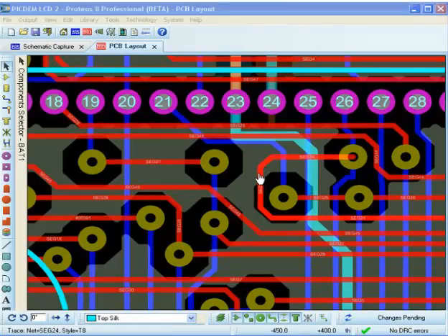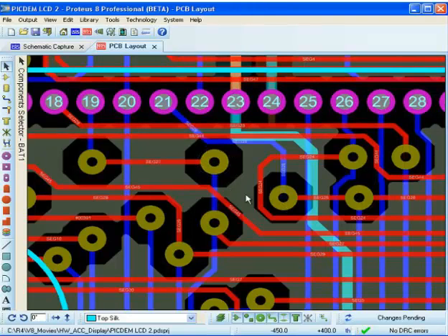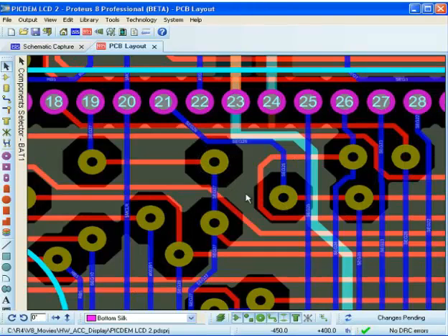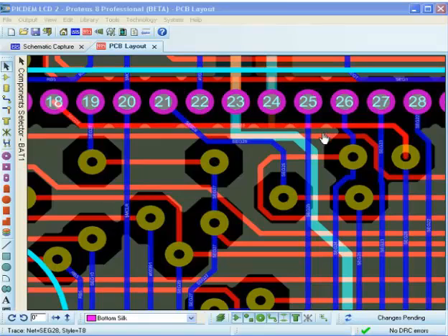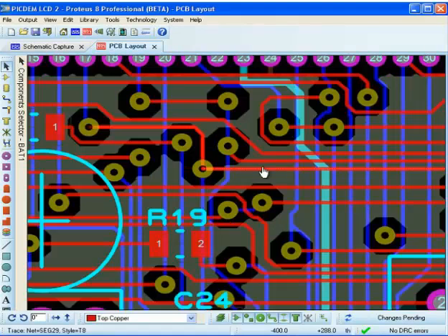The red layer is currently selected and is being shown most prominently. If we select the spacebar, we can switch between any of the pairs that are identified and therefore see the adjacent pair. The pair's layers are controlled on the Technology tab.